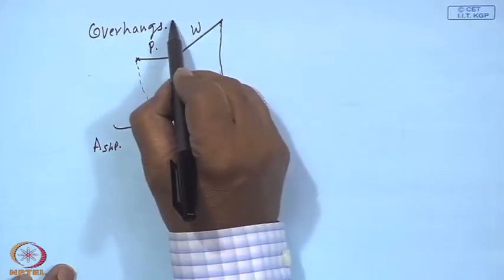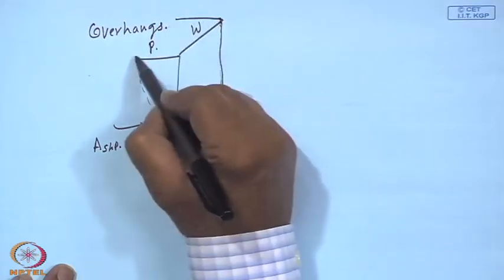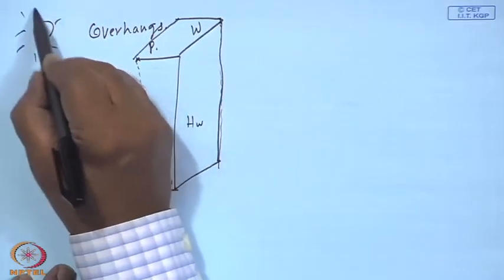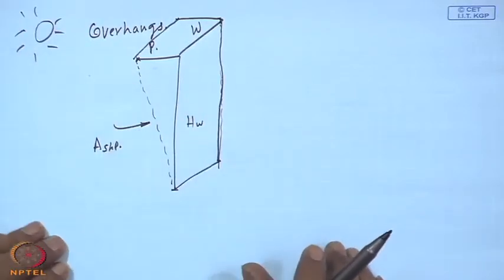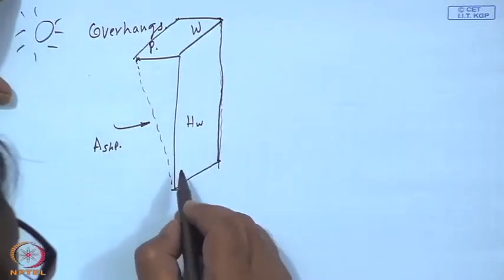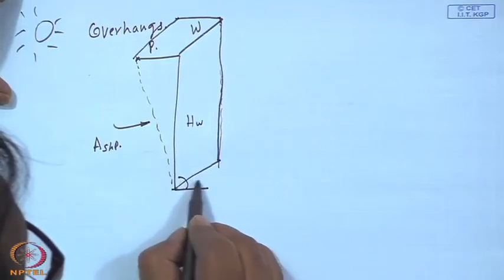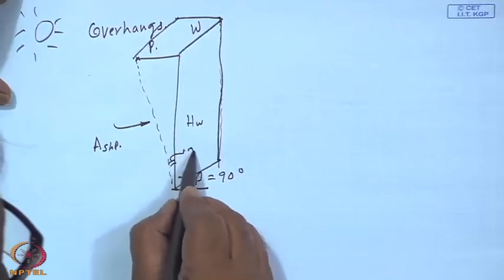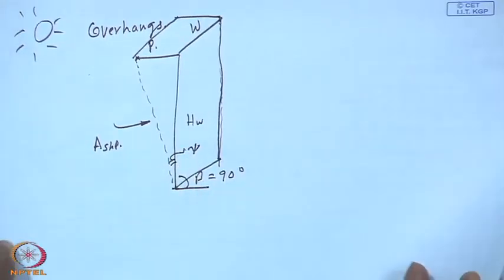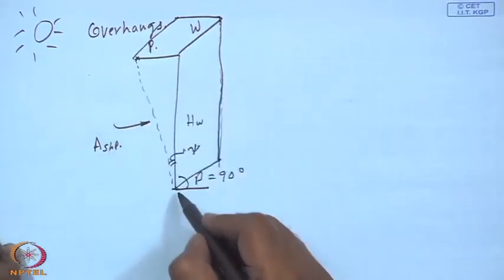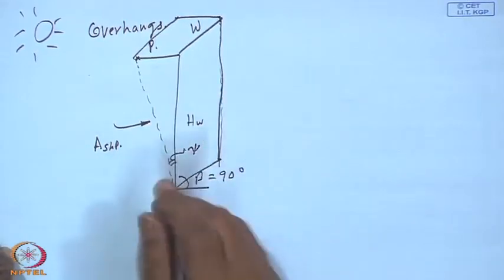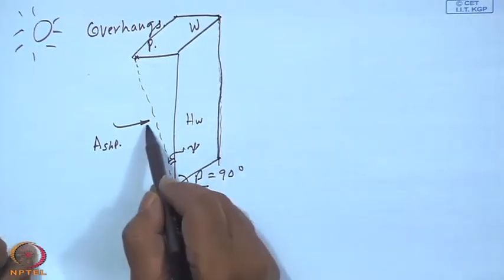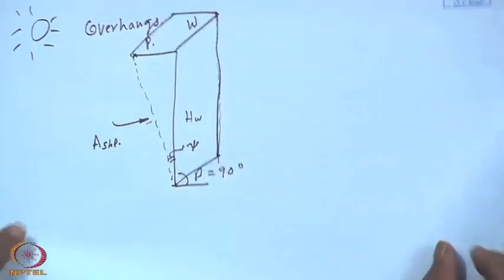This can be a solid line. So, this is what it is, and the sun is somewhere here. So, your RB and RB bar concept can be extended. Of course, generally beta is equal to 90 degrees, and this is your psi, the additional angle. So, essentially it is a surface tilted with 90 plus psi or beta plus psi in general, and you calculate whatever is the radiation falling through this, it will reach the window.